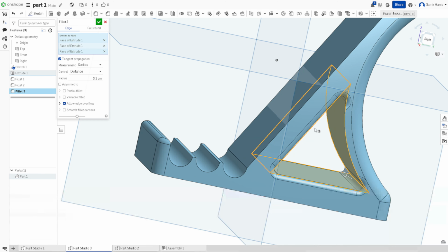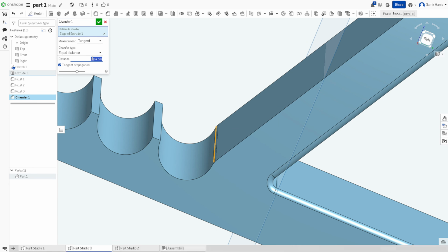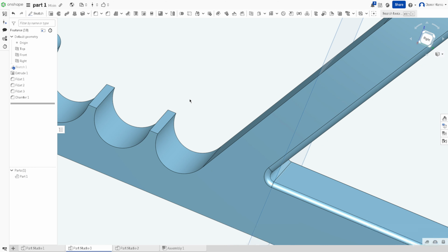But you see, this doesn't look very nice, and it's probably going to stop the phone from entering the hole. So we're going to use chamfer, put it on the line, and we can increase it from some small value to maybe, let's try 1. It looks better, but let's say 2. I think we're not changing anything more, so this is it.